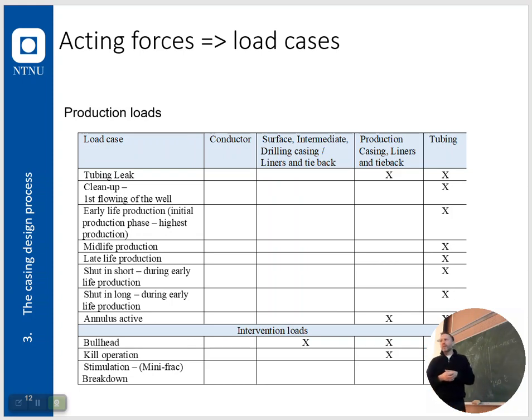Why? Because there was an incident in an old well where they had poorly cemented the production casing over to the conductor, so that there was some leeway there, and they put up these old enormous BOPs without any support. The wellhead had to take all the stress, and you have the ocean current going like this, and you have the frequency swaying of the riser. It broke off the whole wellhead. That happened many years ago, and that's when they started talking about wellhead fatigue as a huge problem.